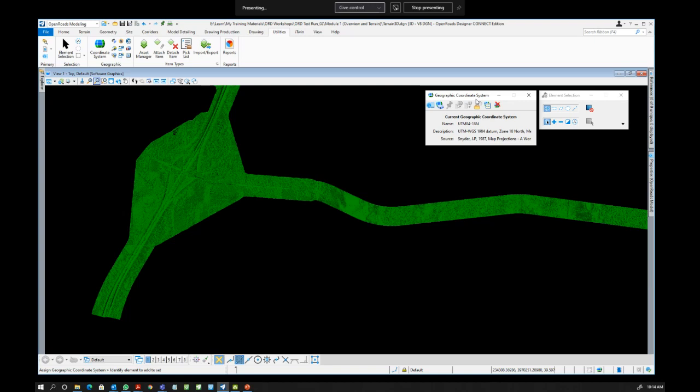As long as you have an internet connection and you have the coordinate system assigned, you can enable a background map, be it satellite image or raster map, or the vector map coming from Bing. Okay, so how do you enable that?